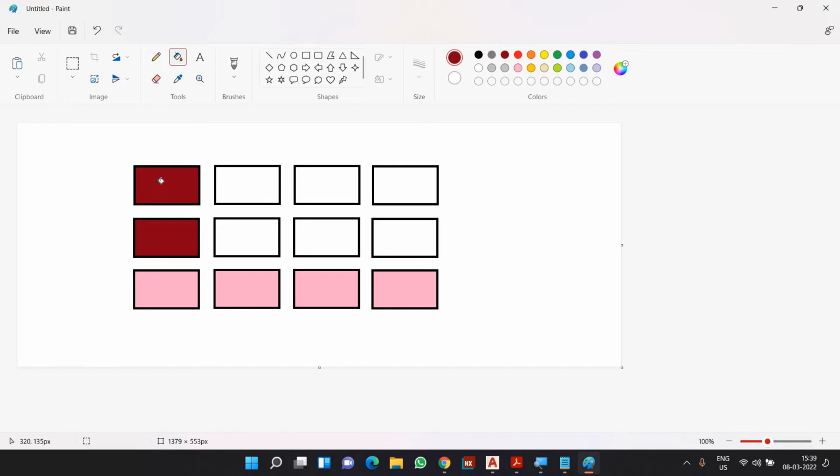Now in the software, when we are defining an array, we have to define a few things. Number one, what object we are going to array, the primary object using which we are going to create this arrangement. Number two, how many rows and how many columns are going to come. In this particular example, we have a total of 3 rows and 5 columns.